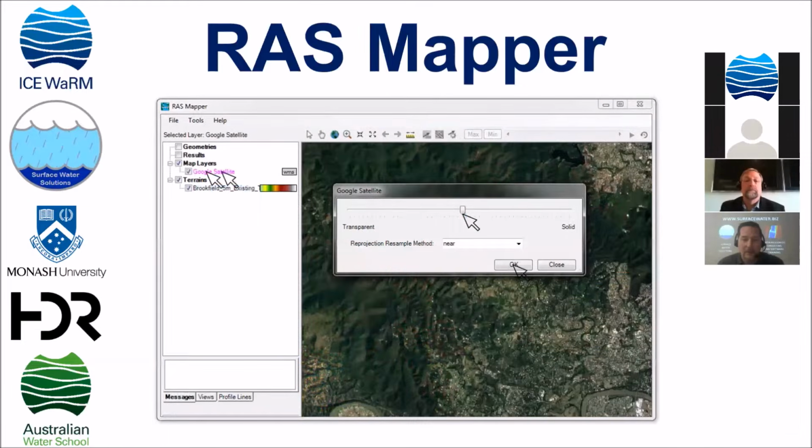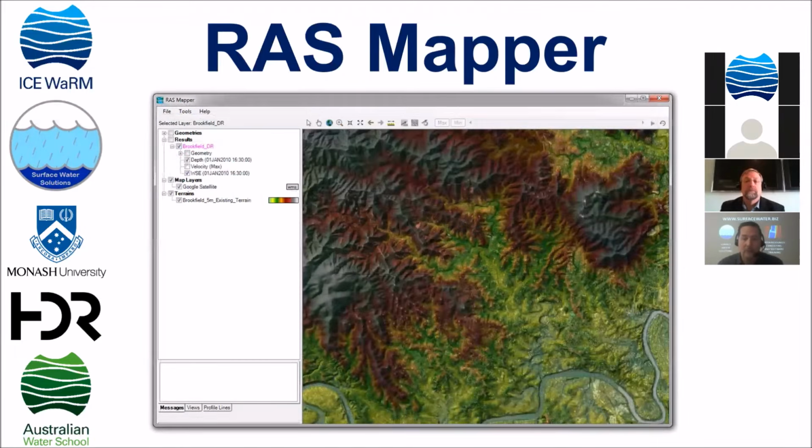It'll overlay it on top of your raster image, but you're not going to be able to see your raster image down below it, your terrain data, until you make it a bit transparent. And I like to balance this a bit so that I can see terrain data, see where I'm at elevation-wise, and also see the buildings and the bridges and the rivers underneath it. So on the next slide, you'll see a merged set of data where you're able to see the buildings underneath, but still discern the catchment boundaries and the things that you're going to need to pick up elevation-wise.